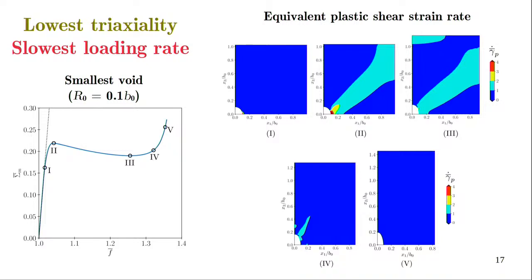With the increase in loading or with the increase in void size, the shear band keeps growing throughout the cell and the plastic strain starts developing throughout the cell. Now when the hardening starts coming into the picture, the plastic strain rate again decreases, and ultimately at 0.5 plastic strain the rate is almost 0, or very small. So basically the whole cell is now expanding at a constant strain rate, like a unit cell, or kind of a homogeneous plastic strain. That is what we can say when the void is smaller.